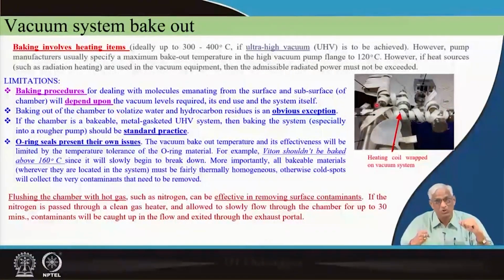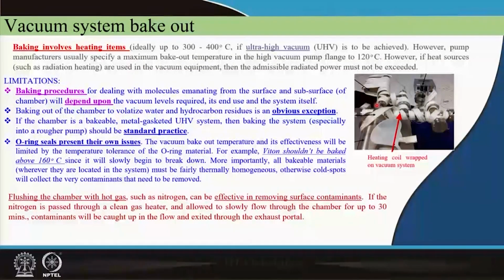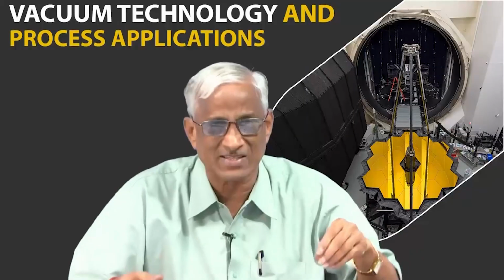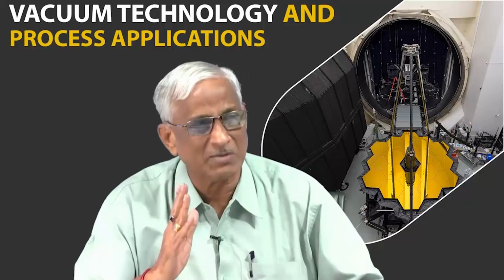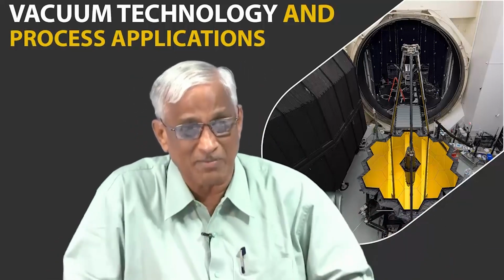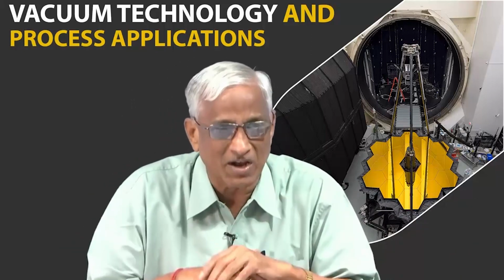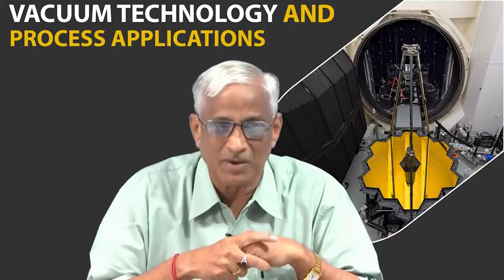Then pumps will initially be used without starting the actual process like the semiconductor process, first only cleaning operations. By removing these gases with the same pumps, you then get a very good ultimate vacuum, which is related only to the unavoidable leaks, which we are going to ignore later, and then raise the pressure with your gases, if it is semiconductor growth or plasma depositions, etc. And the working vacuum can be a little 1 or 2 orders beyond the ultimate vacuum which we get on a blank of vacuum. You have to take care of all that. We will discuss these things in the application areas.